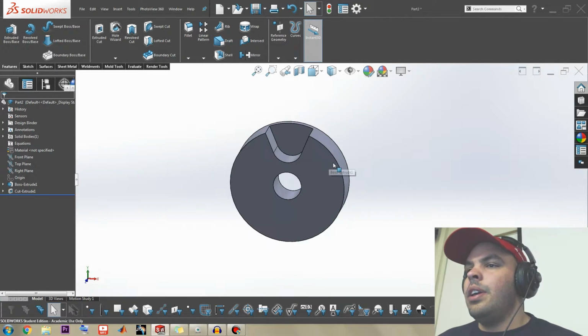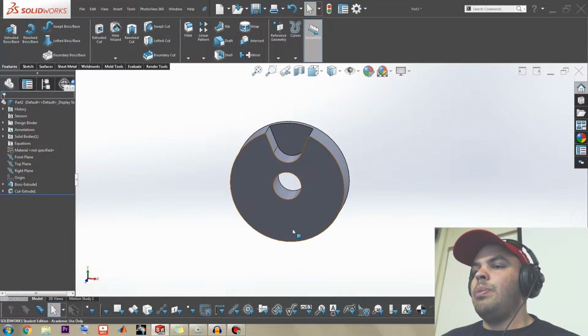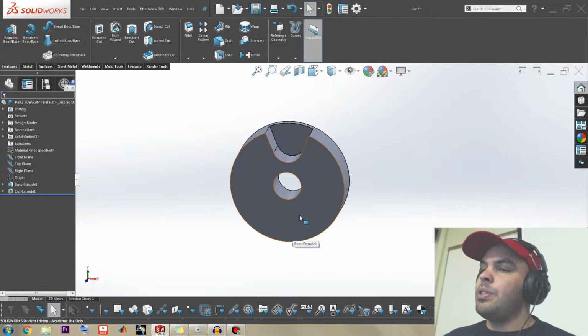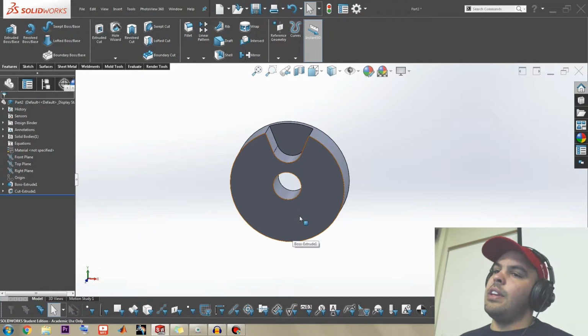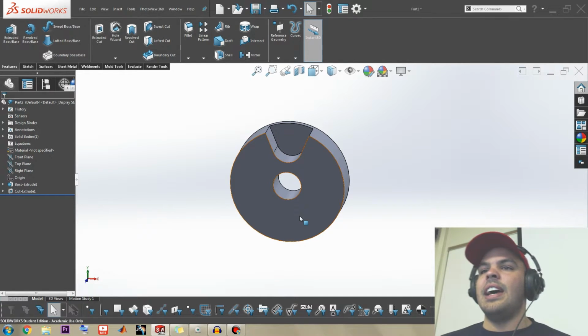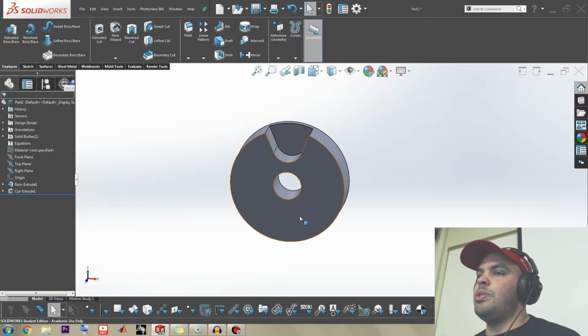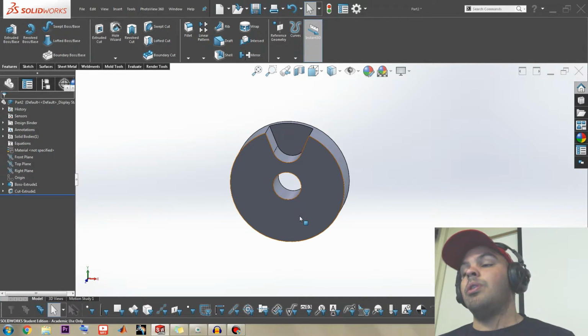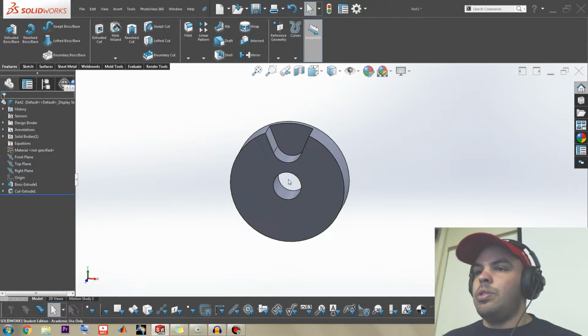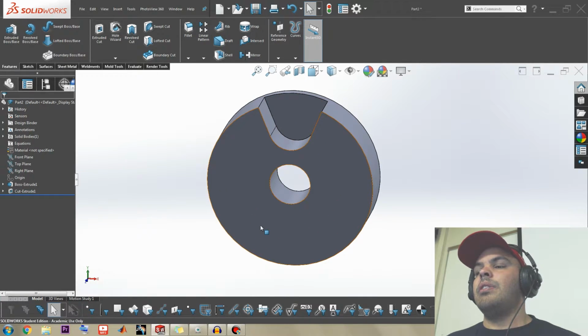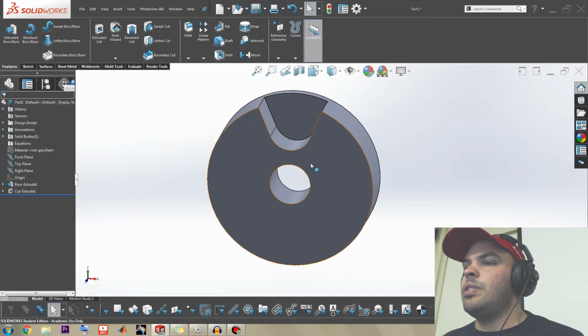So you have that thing, and from this point you can do a mirror, but when part 2 comes along, and that's the funny thing about Model Mania, sometimes you just have to have good intuition or just see the future, so you don't use a mirror but use a circular pattern, because instead of 2, part 2 has 3 instances.